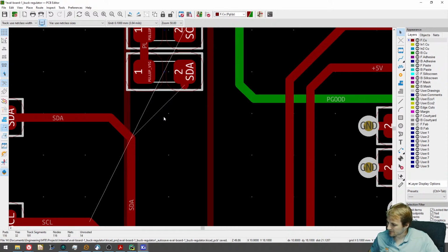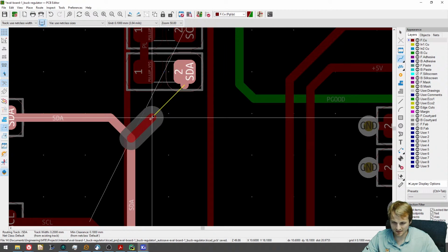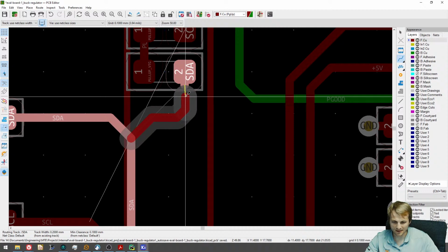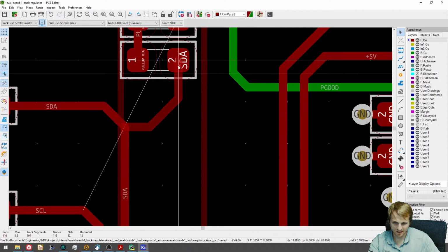Okay, from what I've read, the filter on the V sense pin, if the load is really far from the regulator and you are sensing the voltage at the load, the long tracks will pick up more noise. Yes, that certainly makes sense. I would expect that to be something that should still be mentioned in the data sheet, at least in brief.